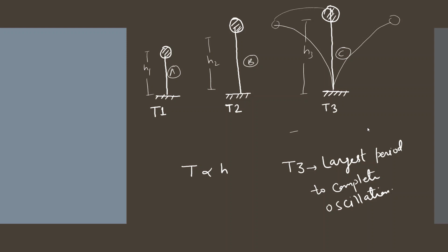It will take maximum time, because as the height is larger, it moves with larger deflection, so it takes more time to oscillate. The others will take less time, and the shortest one will take the least time in comparison. So we can say that the longer the structure, the larger the time period. Generally, the taller the building, the larger the time period.